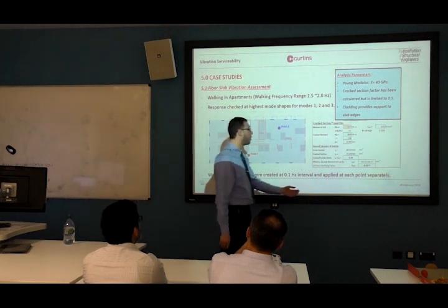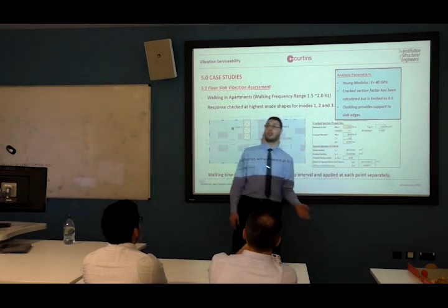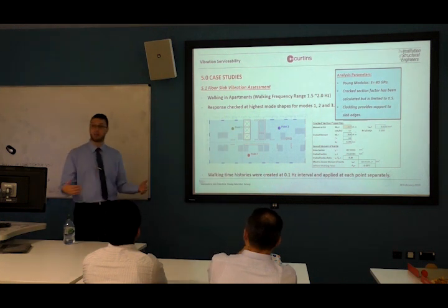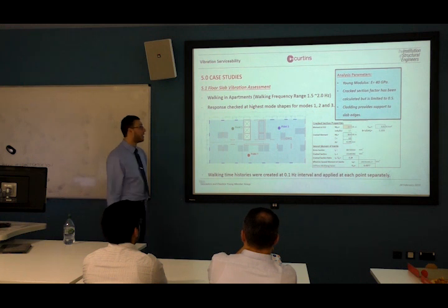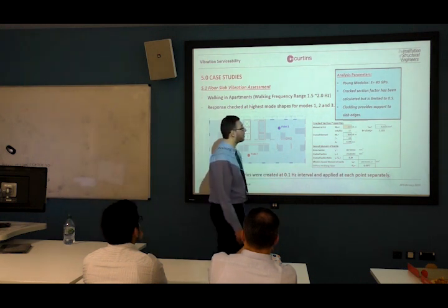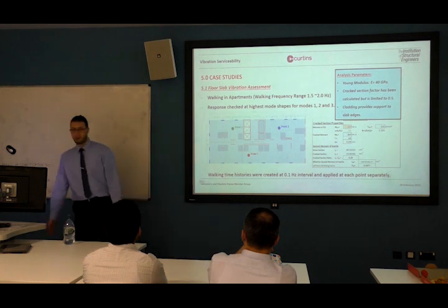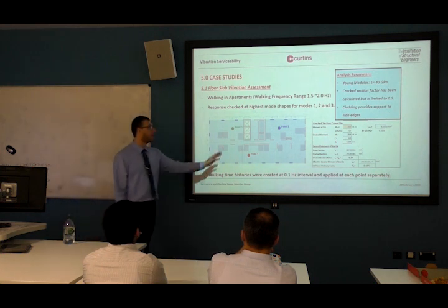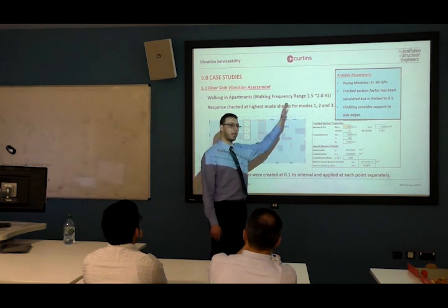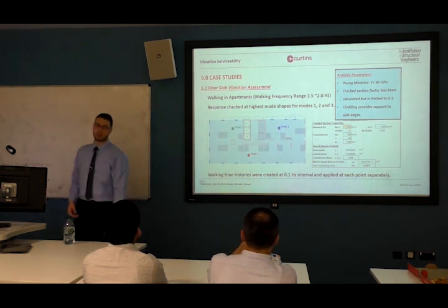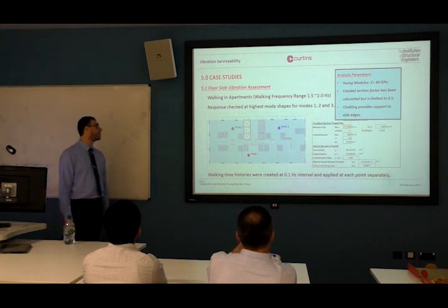We're going to calculate how much exactly it's cracked, taking the SLS moment divided by cracked moment capacity of this slab and check how much it's cracked. But if it says it's not cracked, we're not going to agree with that. We say, okay, it's not cracked, but we're going to crack it by 50%. So a bit conservative, but this is for the peace of mind of the client.